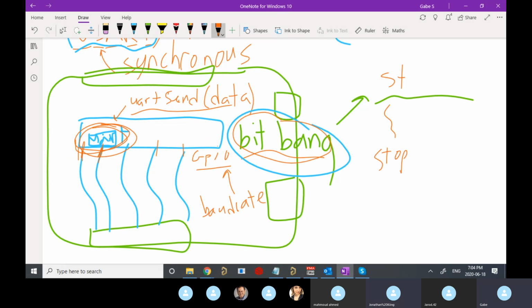Okay. Yeah, I was under the impression all the controller was like a brain or not like some small stuff like that. Yeah, so in the microcontroller you have the little processor brain part, but then for every peripheral, even for GPIO, there's a lot of little hardware inside the silicon that's designed to do one thing really well. So either be a GPIO really well, be an ADC pin really well, do UART really well, SPI, I2C. And so that's the optimized way to go, and it's going to be the fastest way and the least effort. But it is possible to do it yourself. It's going to be a lot slower and a lot more work.